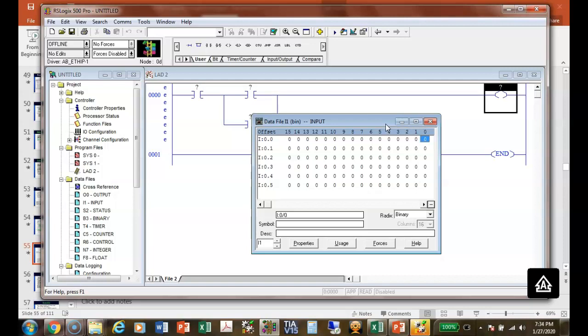This guy, though, first I/O port is going to be in slot 1 because in the rack PLC, the CPU has to occupy a slot, right? In a fixed PLC or a hybrid PLC, the CPU is not in a slot, but we've got to address the integrated I/O, right? That makes sense. So the integrated ports are going to be at slot 0. Are we okay?